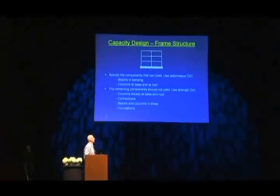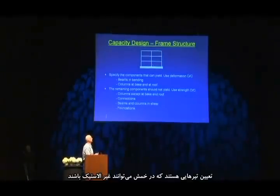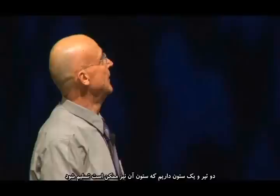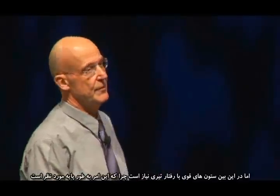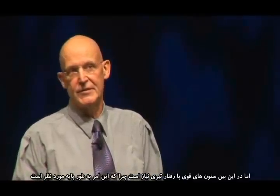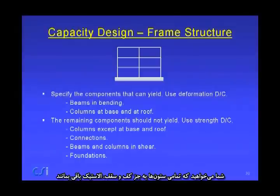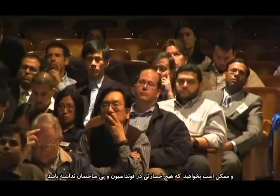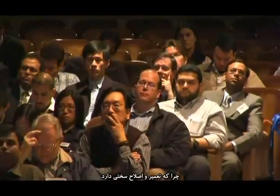For a frame structure, typically what you would do is specify that the beams can be inelastic in bending, and maybe the columns can yield at the base because it's hard to stop them, and at the roof where you've got two beams and one column, maybe the column can yield there also. But in between, you'd want the strong column, weak beam behavior because this is basically desirable. And so you'd want the columns, except at the base and the roof, to remain elastic. You might want the connections to remain elastic. You might want beams and columns to remain essentially elastic in shear. And you might want no damage in the foundations because that can be difficult to repair.